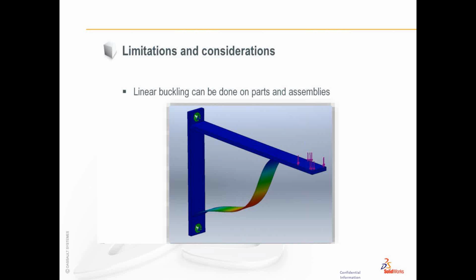That means we can't have no penetration contact conditions where two parts that were separated may be coming together or sliding across one another, because any change in the physical geometry is going to change the geometric stiffness of the component. I'm not talking about the stiffness of the materials themselves necessarily. I'm talking about the stiffness of the structure as a whole due to its geometry.